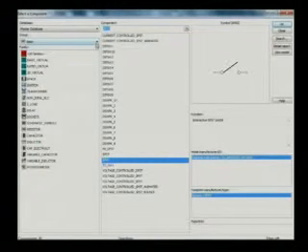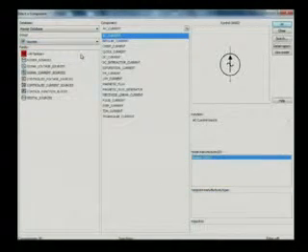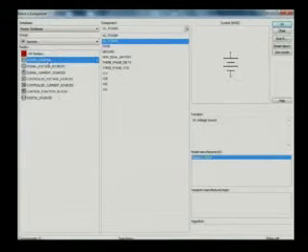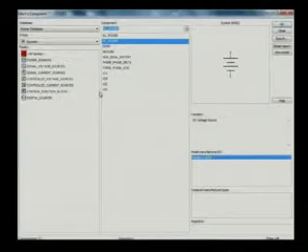In that I want to have one voltage source, that battery, then one resistor and then one ground, for just verifying Ohm's law. So I will go to the sources, and then I will select power sources. In those power sources, you see the DC power, right? I will just press OK. I will get that DC voltage.